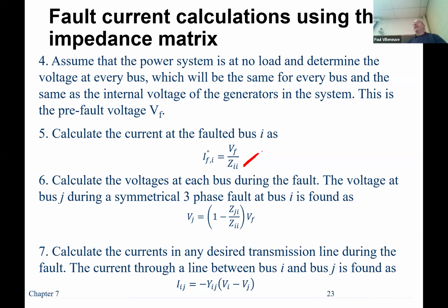Even though you have more important lines, like 345 kV lines, which are almost always what we call bulk power system requirements, which means you have to have 2 redundant channels and 2 redundant communication paths that are generally kind of separated from each other, and even with all that reliability, you still want to have some backup. So you would implement a standard step distance.